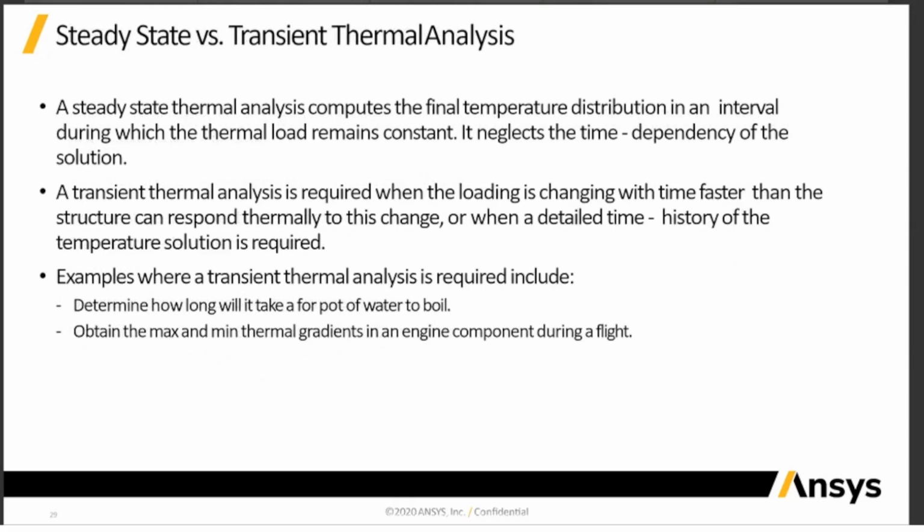Now we will be discussing steady state thermal analysis versus transient thermal analysis. Steady state thermal analysis computes the final temperature distribution in an interval during which the thermal load remains constant, and it neglects the time dependency of the solution, whereas transient thermal analysis is required when the loading is changing with time faster than the structure can respond thermally to this change, or when a detailed time history of the temperature solution is required.